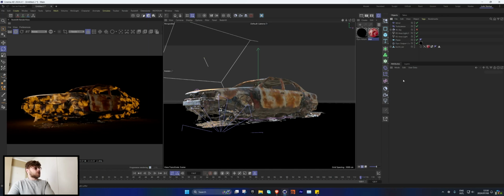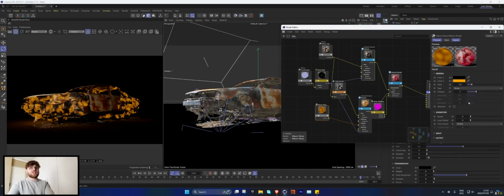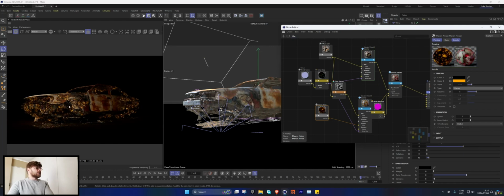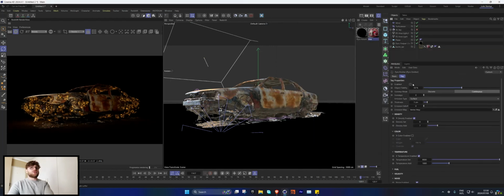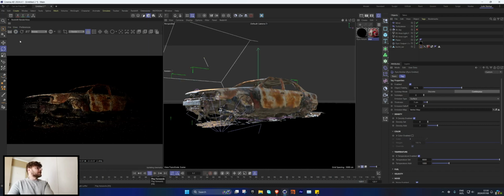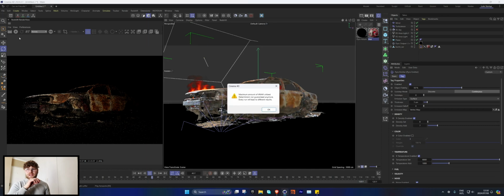Okay, this doesn't look very realistic. Spend a little bit more time adjusting this, try different looks over here. I mean, actually that looks pretty cool. And let's maybe just make this like 2. And just like that, if we turn on our fire over here and resimulate, we can get a nice realistic kind of looking texture. Now as it grows, it burns the actual car, so it makes it black, and also has the glow to it as if it is burning it.